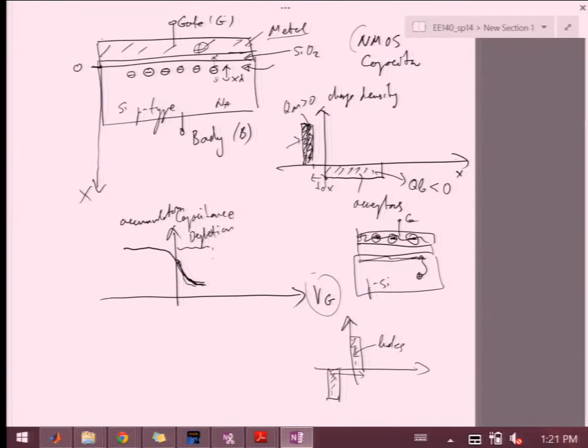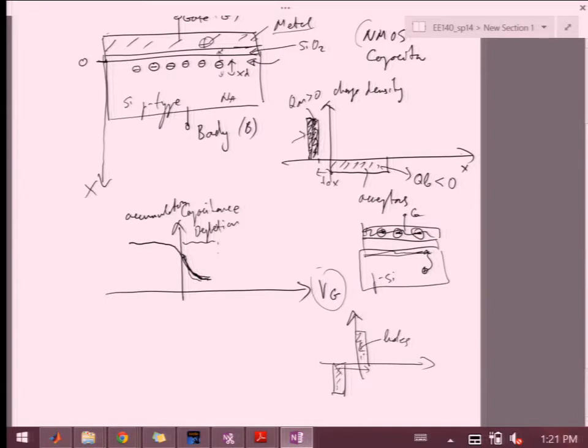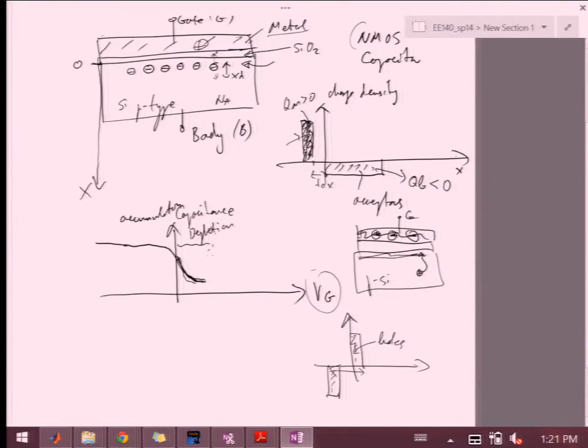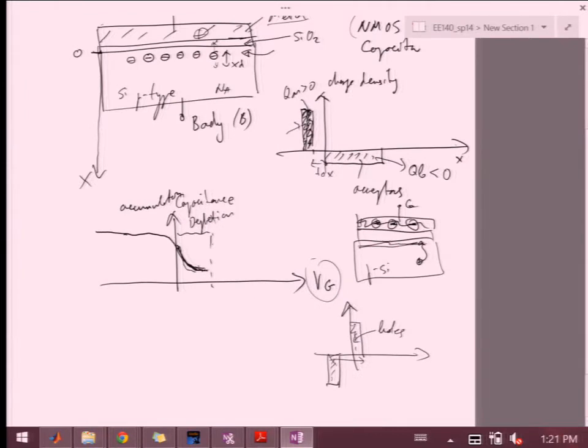Okay. And once they get slapped over here, there's really no change. I changed the voltage. There's just more charge, essentially. But my capacitance value doesn't change, right? Now, the interesting thing starts happening on this side, where as I'm increasing the positive voltage, the depletion region expands, but does that very weakly, right? If you recall the equation for the depletion region, it is kind of a square root dependence on voltage, right? So it's very slow after a while.